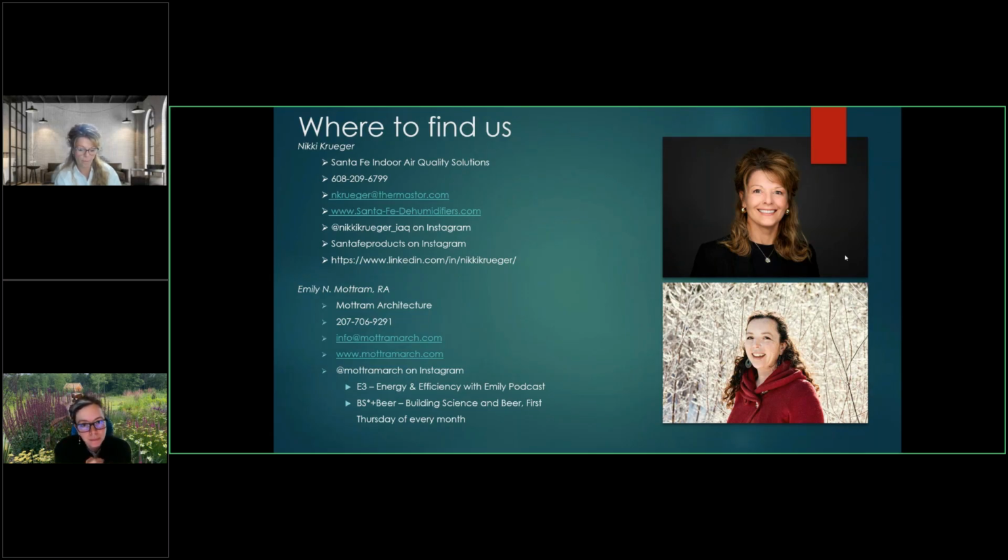Yes. So maintenance is number one. All of the systems, 100% agree, maintenance, and change those filters. If you have someone who's sensitive, we say 3 to 6 months on ours. If somebody's using ours for ventilation and not just dehumidification, I highly recommend changing that filter every 3 months. If they're sensitive, what is going on outside and what they are doing inside will determine how often those filters need to be changed. Also, clean the condensate lines, just like the HVAC system.